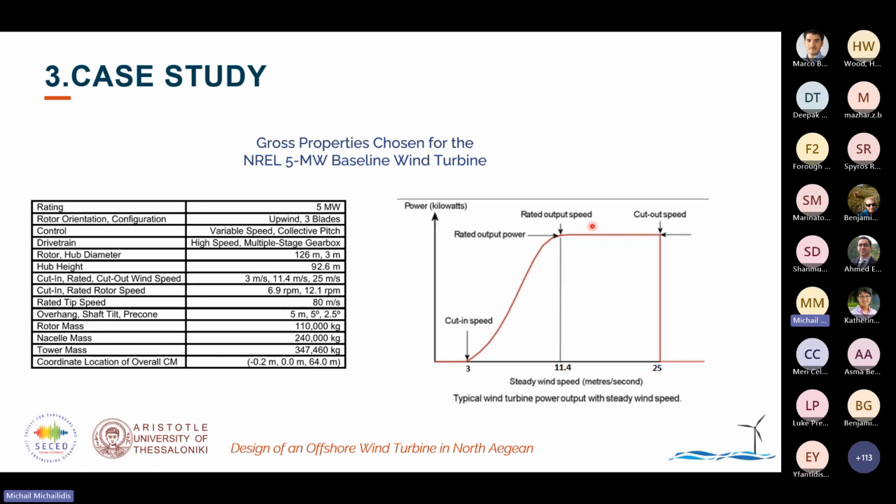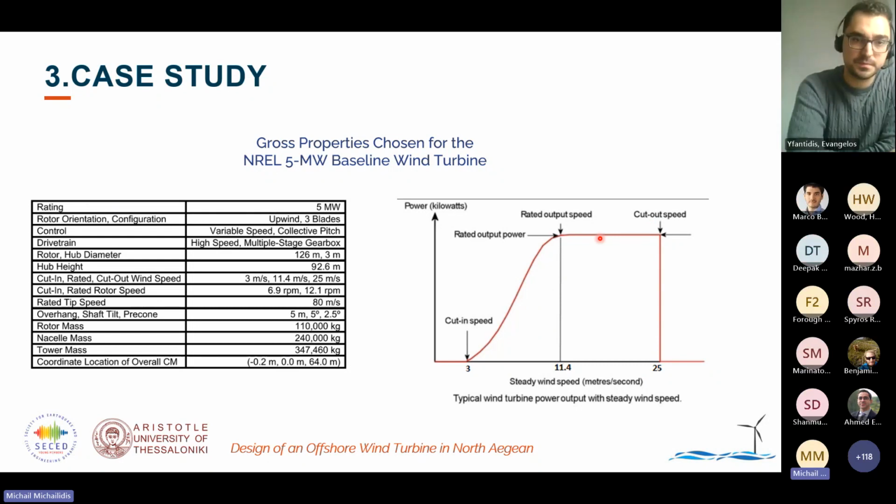second. So across this area, the wind turbine operates in the power control, while from the rated speed to the cut-out wind speed, there is a transition from power control to pitch control, where each blade rotates about its own axis from 0 degrees to 90 degrees, where this goes later to the idling mode. During the pitch control, the wind turbine operates a constant wind power production of reference, which in this case is the 5 megawatts.